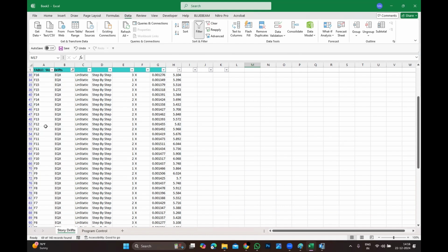Now see, the question is what the importance factor actually is. I'll tell you something. When you are designing a hospital building, the importance factor is 1.1. When you are designing a military building, it is 1.2. When you are designing only a residential building, commercial building, or office building, it is all 1. For other buildings, you need to take the importance factor accordingly.